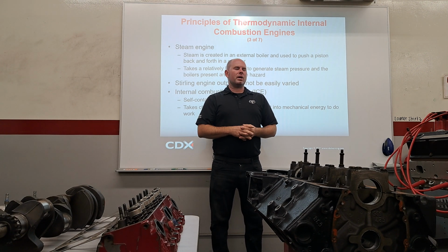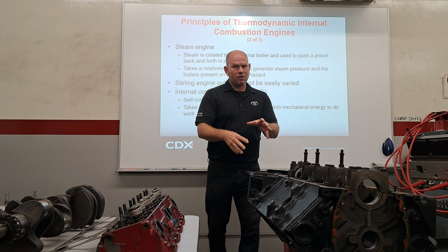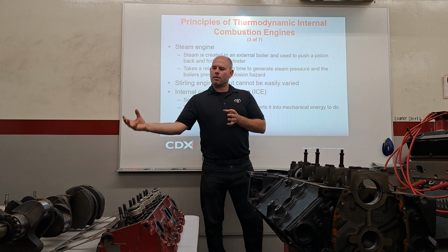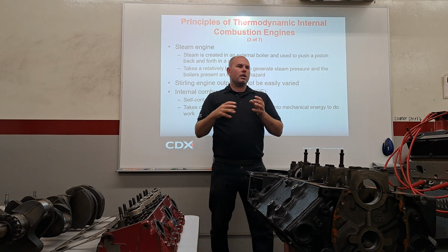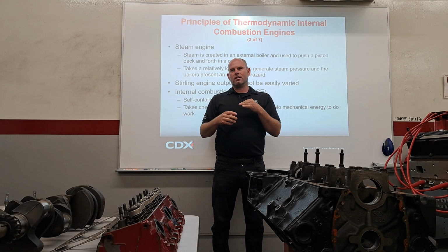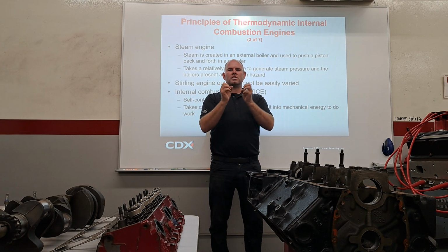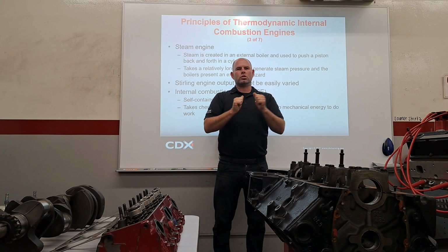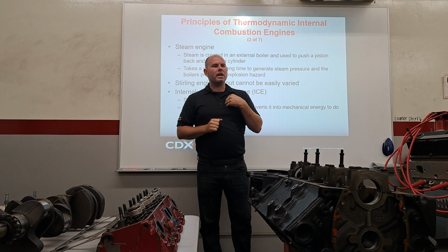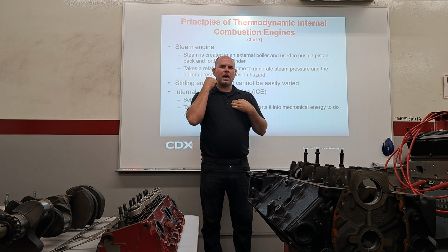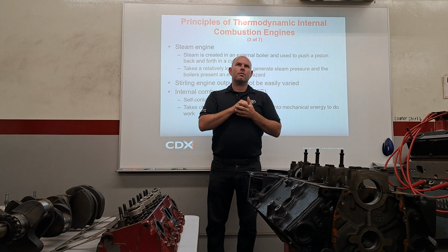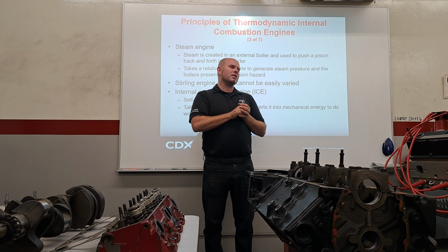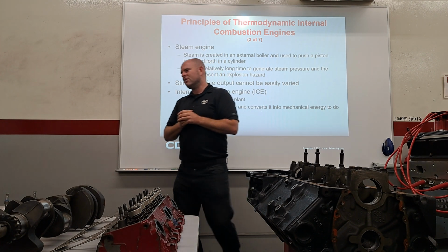But you can't just throw gas at it though. It's got to be in the right ratio. So if you want to be able to put more gas in it, you need to pull more air. If you pull more air, you can pull more gas because they have to be in a ratio, like an air-fuel ratio. So we're trying to make the engine breathe better so we can add more gas and get more power, but then there's bad emissions, and you go to the smog check, you get cars getting repo'd, all that type of stuff. So that's basically what it does.